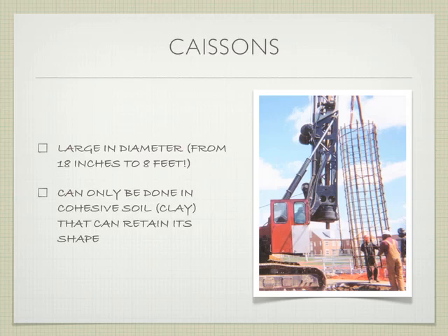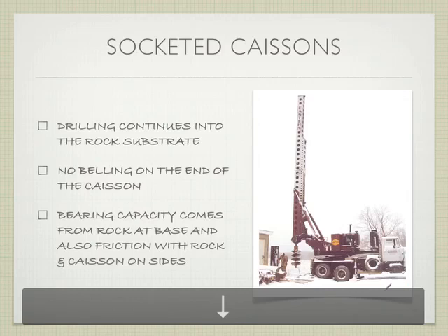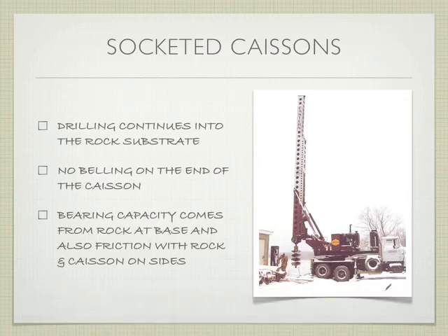So, again, these types of foundations are really specific to the conditions of the site. What kinds of soils do I have? Or what kinds of soil do I have to go through? If you had clay on the top, that's great. But if we continue to drill down and we hit a layer of sand, that's problematic. So we have to be very careful with what's happening, which is why those test bores are important, so we understand. So, socketed caissons.